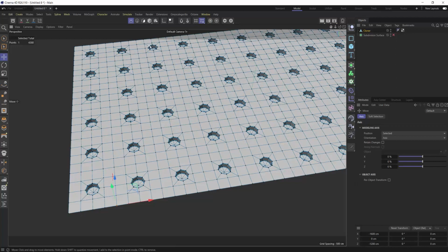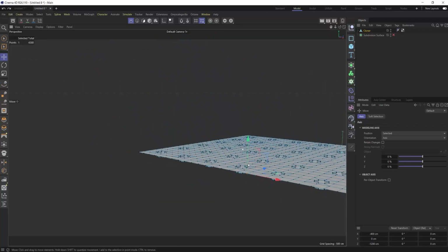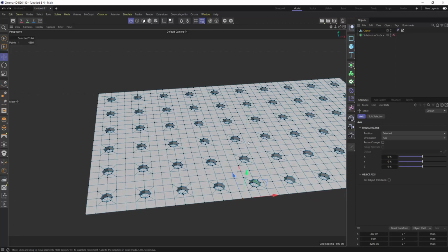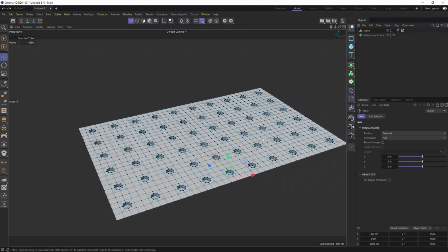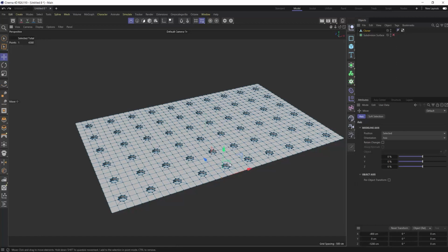And they're going to give you these kind of issues where you think an object is connected and it's just not. And if you have these kind of issues, you're not going to be able to UV map it. And proper topology is really important when we get to UV mapping, which is what our end goal is here. And that's what we're working towards, really great textures. But before you get really great textures, you have to have really great topology.